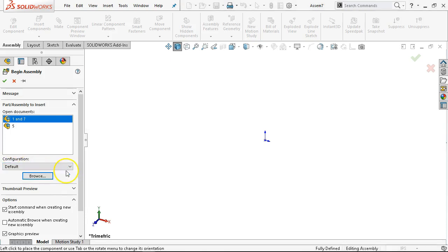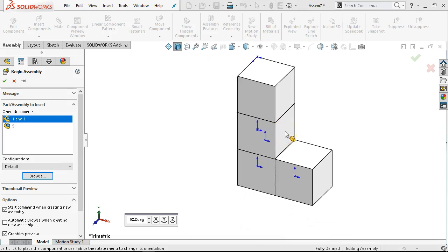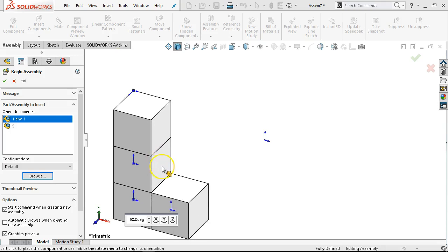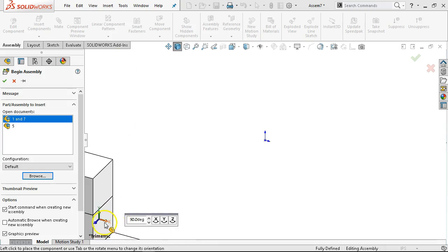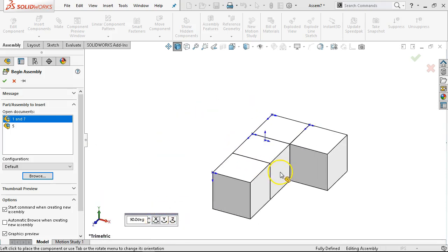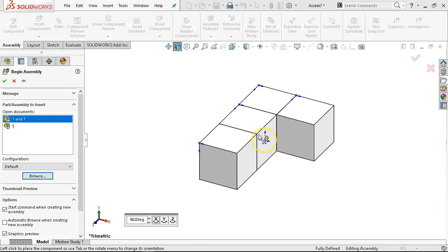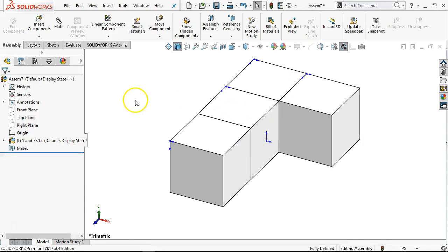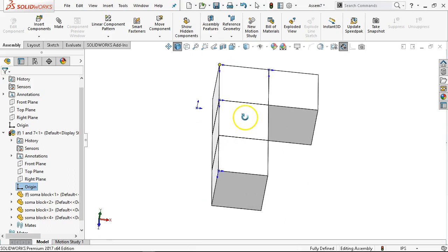I can do the pull down, go back to the default, and it will come back as the 4-block L-shape. Let's rotate it. So I'm rotating about the x-axis. Rotate it 90 degrees. I think I can work with that. And then we'll go origin to origin doing that. So it went fixed and origin of the part. Well, that was up there. So no, not really.